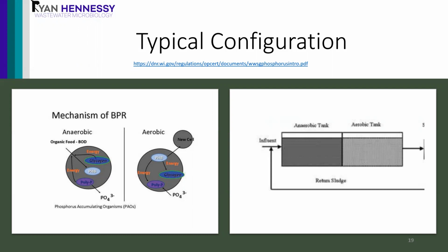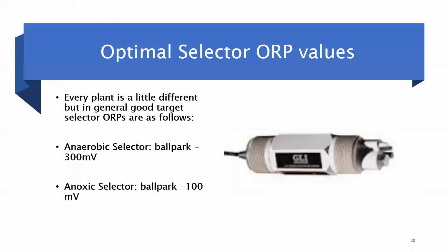So you may see 5 in the influent and 15 to 20 in the anaerobic. And then as you get to the aerobic and you start to get those PAOs, it's a process called luxury uptake, where they're really rapidly recovering that phosphorus that they had to release in order to store that food in the anaerobic zone. You can get very low phosphorus left over residually.